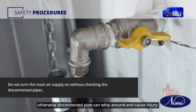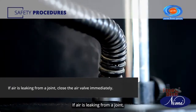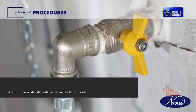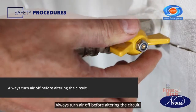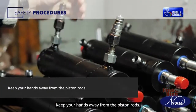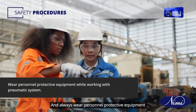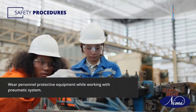If air is leaking from a joint, close the air valve immediately. Always turn air off before altering the circuit. Keep your hands away from the piston rods and always wear personal protective equipment while working with a pneumatic system.